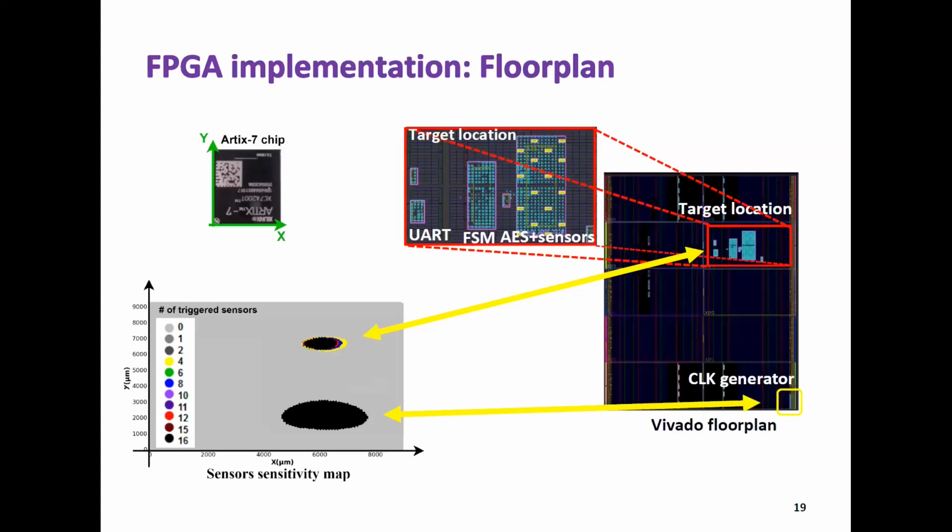But if we do a full cartography, you see that all 16 sensors are triggered because I do a coupling with the clock generator. That is why all of them fault on the glitch. The clock is distributed like a tree: we tap the first of the tree and distribute it to all the leaves.